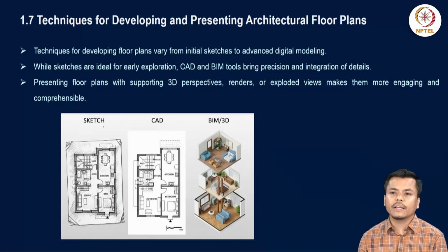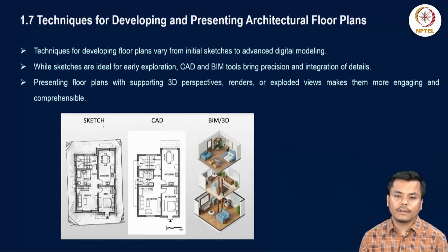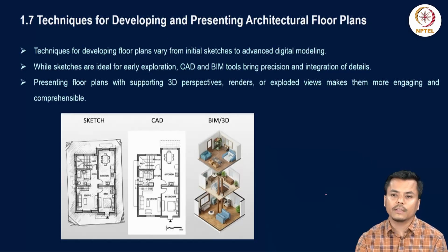So there are a few techniques of developing and presenting floor plans. We generally start with the sketch that we prepare for the particular building, showing the idea behind the project, like the single line floor plan. Then we prepare the double line floor plan in some software, and then we try to develop the 3D views, perspectives or renders for the project, as shown here in the image.